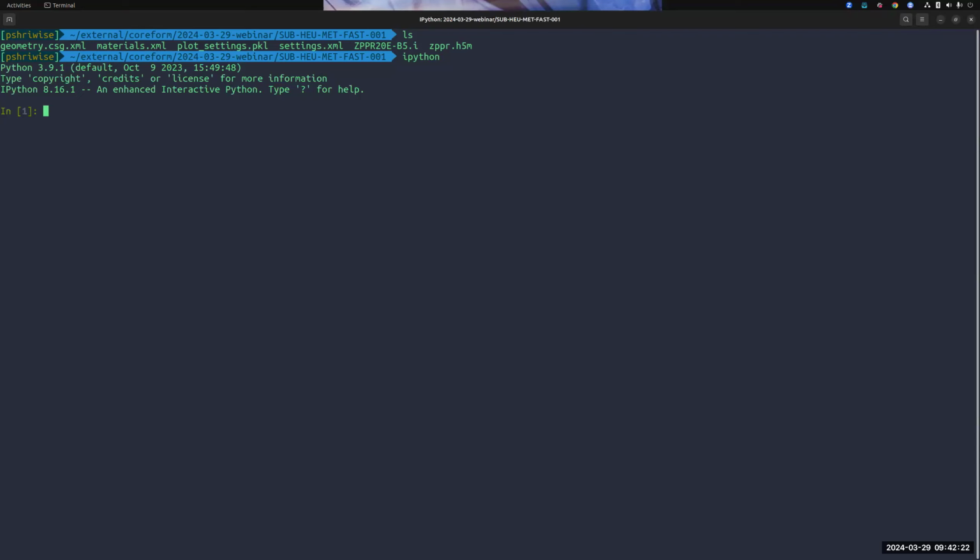And then I'm just going to walk through a little bit on how to generate that geometry XML with OpenMC. So model generation with OpenMC occurs through Python. And if I import OpenMC itself, I have the ability to generate within OpenMC what's called a DAGMC universe. So I can do a DAGMC universe, and all that's required for me to specify is the DAGMC file that I would like to use to populate that universe.